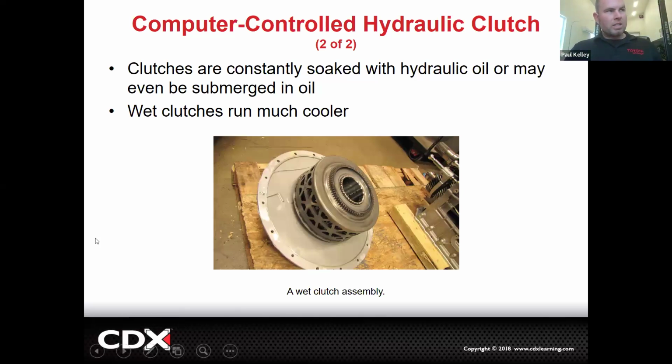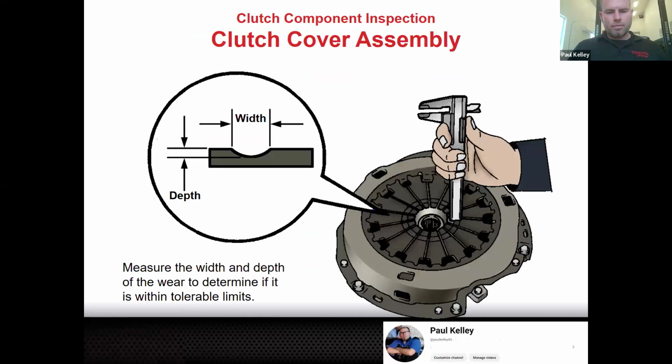Both of them will go into the transmission. This is going to be a multi-disc, right? So you can imagine you're going to be able to put a lot more torque through a multi-disc with 6 or 8 plates on it compared to a single dry disc with 1 plate. Cool. And so for performance, it's probably going to go wet clutch. This is only for dual clutch transmissions. We don't do, as far as I know, wet clutches with a clutch pedal. We just don't. All right.